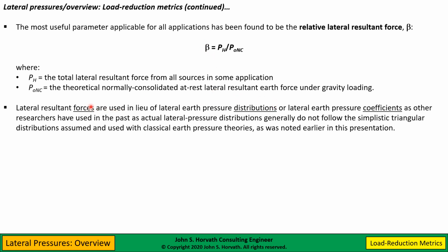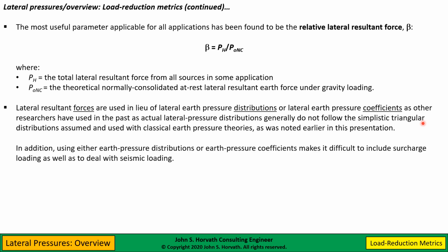I found that using forces instead of pressure distributions or pressure coefficients, as other researchers have used, is really much better, because lateral pressure distributions do not follow the simplistic triangular distributions as generations of geotechnical engineers have been taught. I've mentioned this previously. And also, if you use pressure distributions or pressure coefficients, it becomes clumsy to include surcharge loads as well as deal with seismic loading.